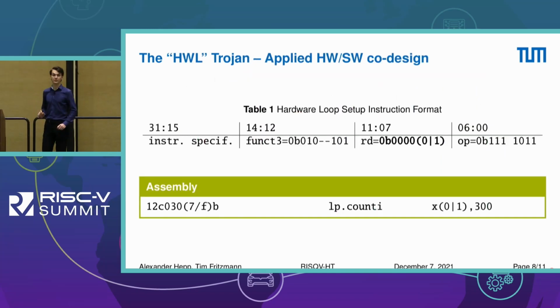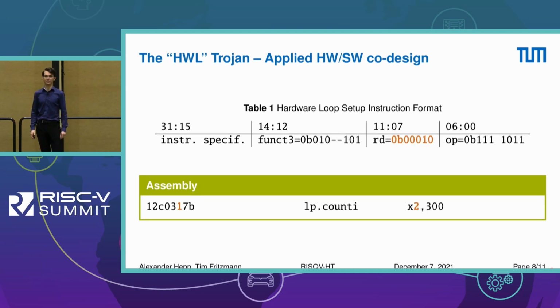So for setting up the hardware loops, you require an assembly instruction. And this assembly instruction can deal with 2 of these hardware loop controllers, meaning you have 2 nested loops in your device for your looping requirements. Fortunately, neither the compiler, so neither the assembler, nor the device itself did note that I can change a bit there, because I can also say, okay, there is a 3rd hardware loop controller there, and I want to set up this 3rd one, which is not in the hardware.